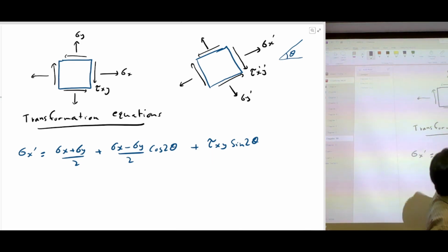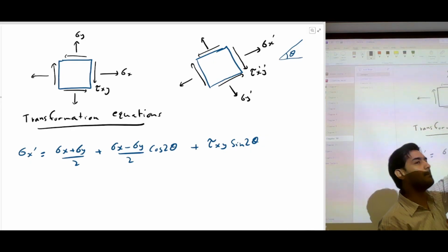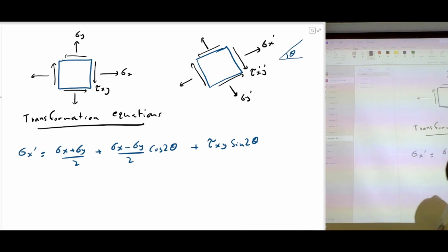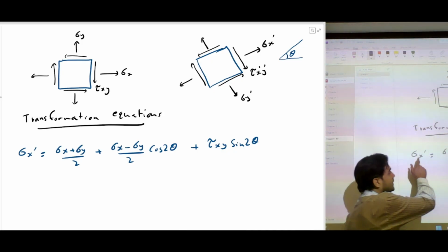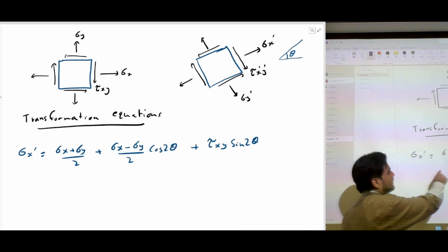We will already get those stress x, stress y, and tau xy from those combined loadings and combined stresses. And if we want to rotate this stress at a particular angle, let's just say 30 degrees, we can get the new transformed stress by this equation.